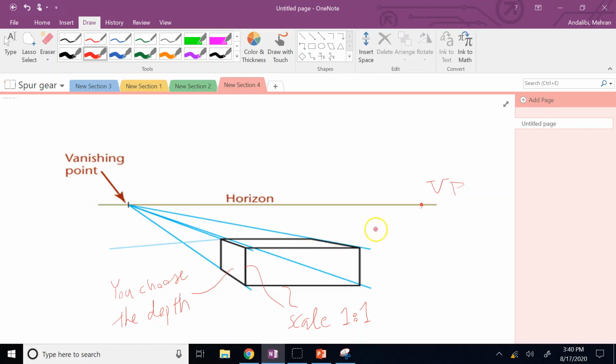So this is how I do it. First, I will connect the vertices all to the vanishing point using dashed lines like this. Right? Then I come here and let me draw this with green. So as I said, the front face, no difference. That's the same thing. So you're going to get the same thing in green on the top of the black.